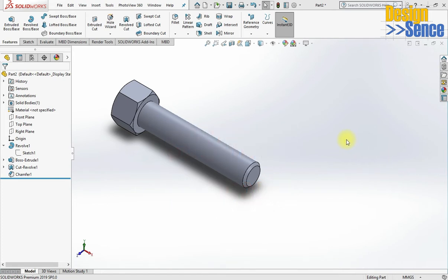It is a graphical interpretation of a thread on any circular body in SolidWorks. It is not actually giving the detailed thread on the shaft or spindle. It only shows the graphical view on that surface, so that you can understand that this part of the shaft is threaded, and you will also get some details in the drafting when you give dimensions and all these things. So that is the purpose of a cosmetic thread.